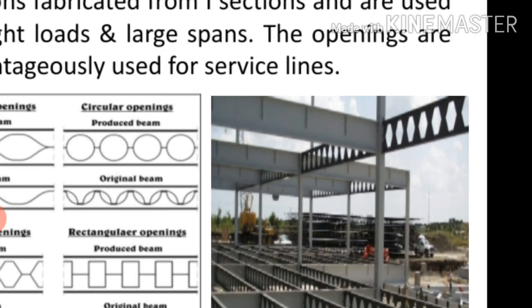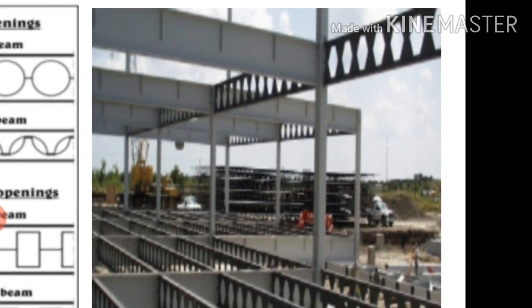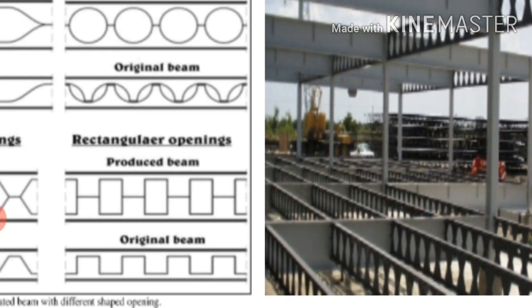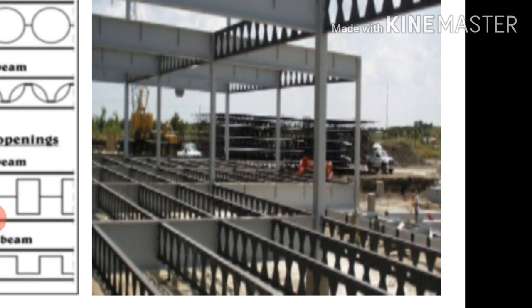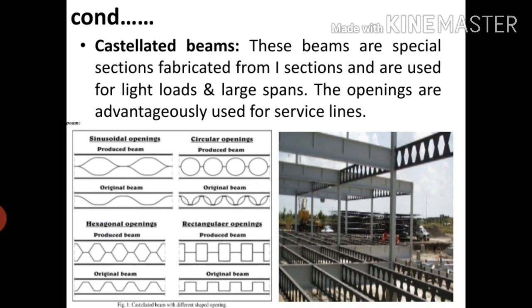So look at this figure, you can clearly understand the castellated beam. What is a castellated beam? At the web of the section, a hole is made, that is the opening is made in a hexagonal shape. See the hexagonal shape. These kinds of beams are called castellated beams. These beams are special sections fabricated from I sections and are used for light loads and large spans. The openings are advantageously used for service lines.